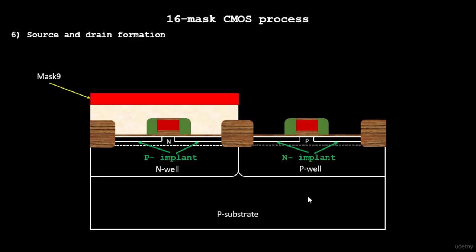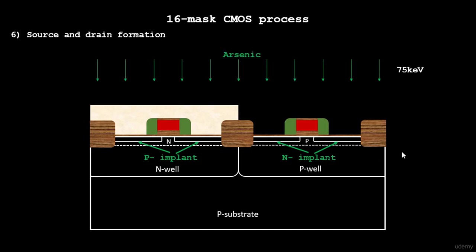These are more of a device physics thing, but let me brief you about these effects. About the hot electron effect: when the device size reduces, the general practice is to not change or redesign the power supply. In that case, consider the electric field formula, E equals V by D. When your device size reduces, D reduces, so your electric field increases. As a result, various effects happen.